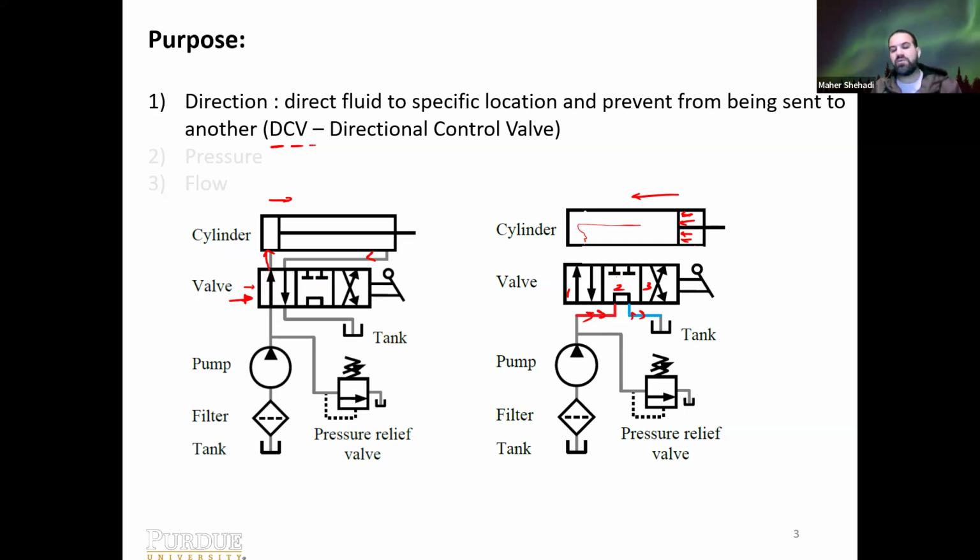In fact, in any system we would put a pressure relief valve, because we never know. Even if you have a variable displacement pump, which means as the load changes, the output from the pump would change as well. So if it feels that we don't need that much pressure, or if we go to the neutral and it's blocked somehow, it should sense the pressure and this should go down all the way. But you never know. Maybe the response is not working, and the pump keeps pumping, the pressure builds up, and you cross the burst pressure of the pipe, and it bursts.